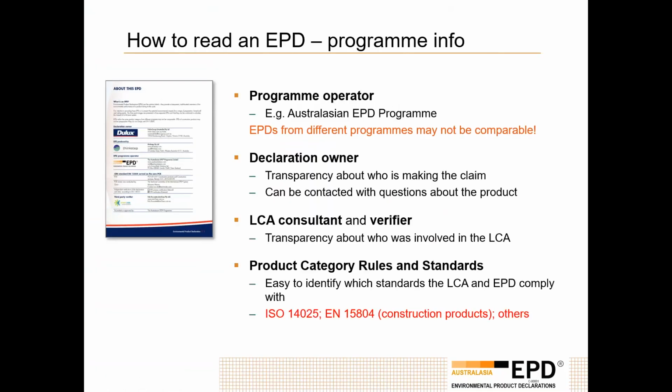So every EPD will have program information, and that states who the program operator is, for example, the Australasian EPD Programme. Now, the reason why that's important is because EPDs from different programs may not be comparable. A lot of people are interested in comparing products on the basis of their EPDs. So one of the first things to do is to make sure that ideally they have the same program operator. If not, you've got to be a bit more careful.